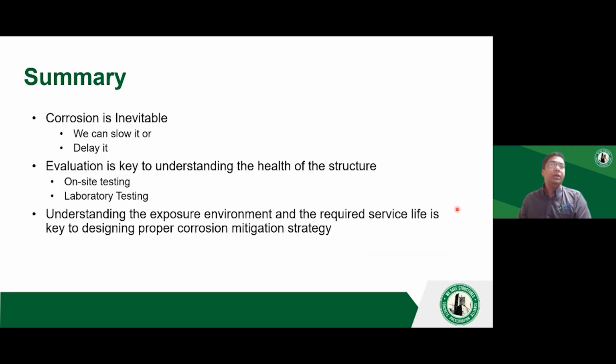So in conclusion, corrosion is inevitable. We can just slow it down or we can delay it. Evaluation using different techniques in conjunction will give you a really comprehensive picture about your structure. You cannot simply rely on just the hammer sounding or just the visual inspections. You need to use multiple techniques at the same time to get more confidence in your data and more information about your structure.